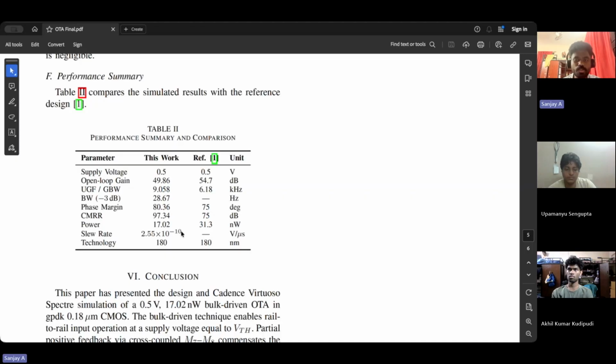The non-tail topology gives naturally high symmetry, which suppresses the common mode gain, and PPF boosts the differential gain without affecting ACM, because PPF acts on the differential signal path only. Together, these push the CMRR well above the reference. In practice, this means 50 Hz mains interference on your ECG leads is rejected by a factor of 232,000. The ECG signal comes through clean.